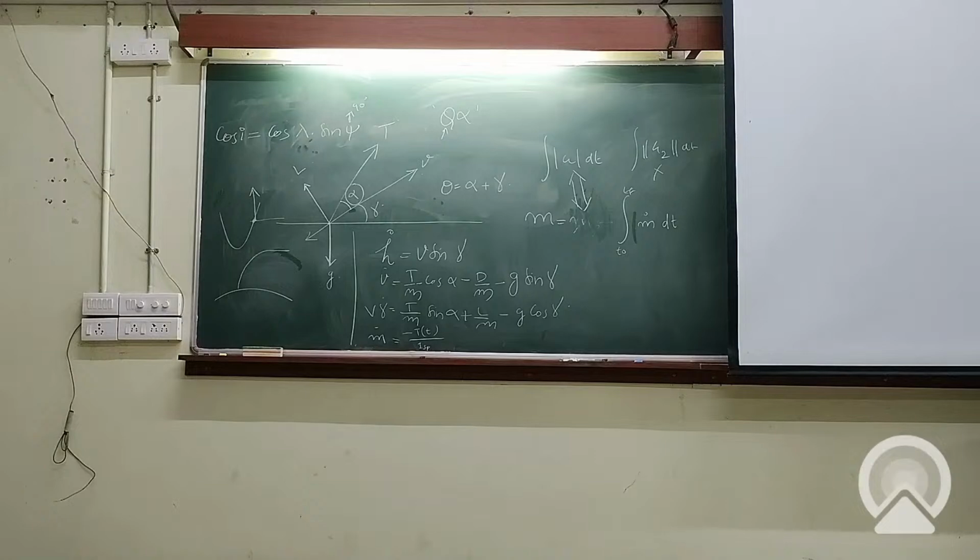Where do we discard it? You cannot discard it at any point. Your altitude should be sufficiently high so that the aerodynamics is less, so the heating is less. That is another constraint. Then you cannot have any rates during separation, as it will have an impact on the separation. There will be recontact. So you should have very benign rates during the separation events.